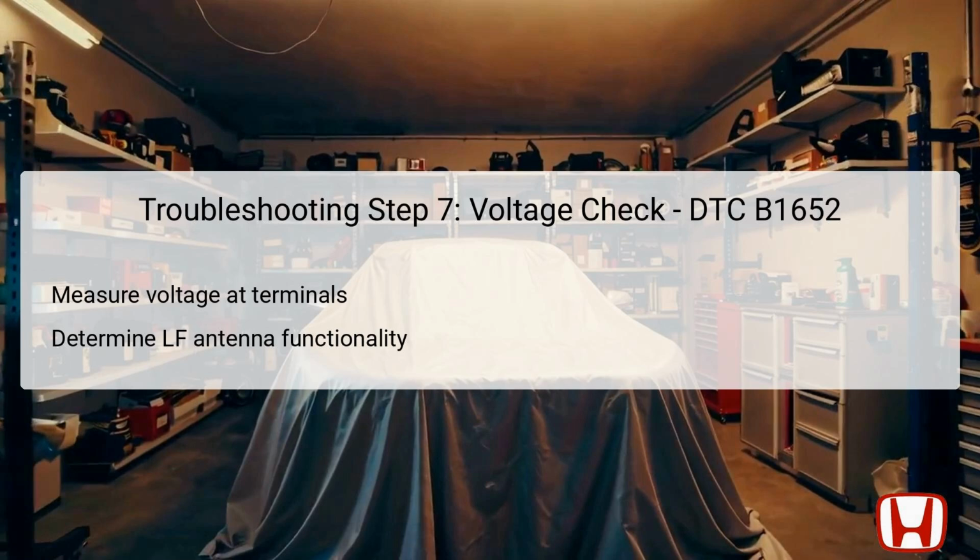During this step, the technician must connect a voltmeter to the 8P connector terminals of the right sliding door outer handle LF antenna. The specific terminals to measure are numbers 2 and 6, where the technician will check the voltage output. This procedure is vital in establishing whether the LF antenna circuit is receiving the necessary voltage, as a lack of voltage would confirm an open circuit condition.